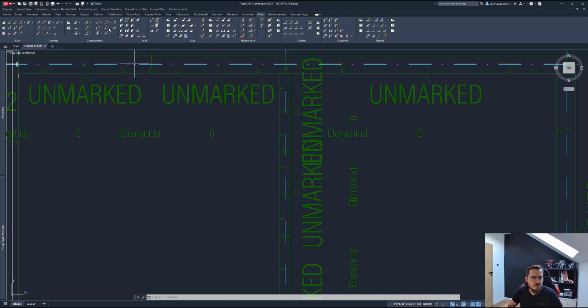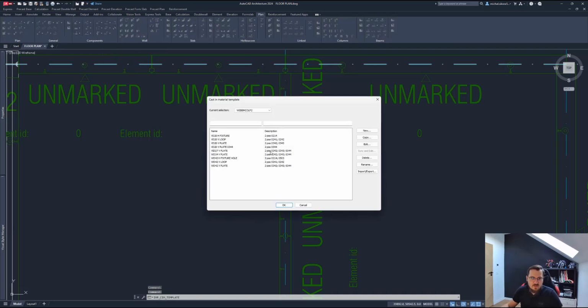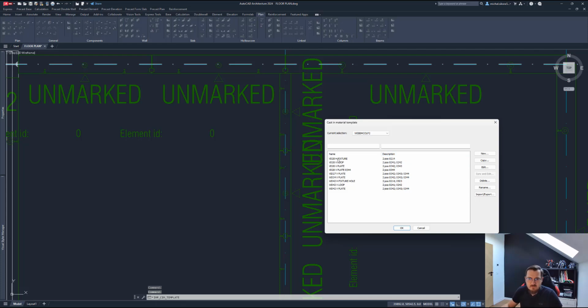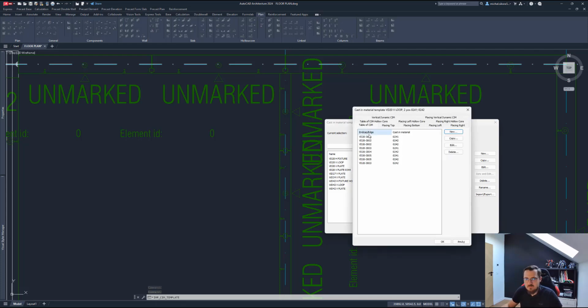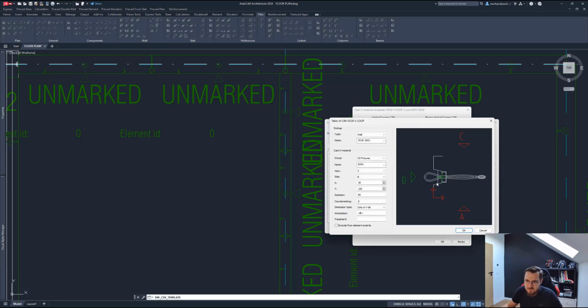So custom material templates, again, quick explanation. What type of wall I have here is for my 20 size wall. I will look for this particular end cap, which I just applied as I split this wall, right? I'll just open it and edit, and I will apply this particular casting material at this end cap. At this location, which is that green cross, I can of course move that, say 50, and it moves inwards. 38 is sufficient, so it looks very nice. And of course, I can rotate that, move that further out. I can also change the angle to 45 degrees if we have some kind of connection like this. Well, let's leave it at 90.